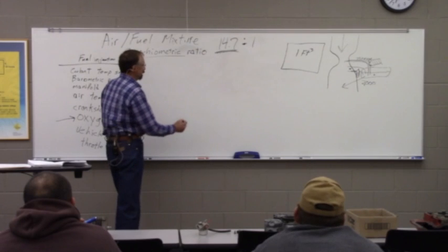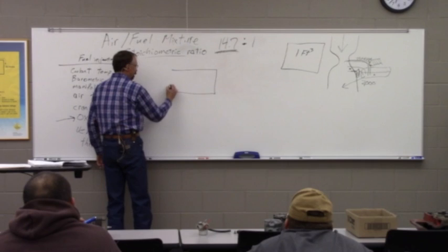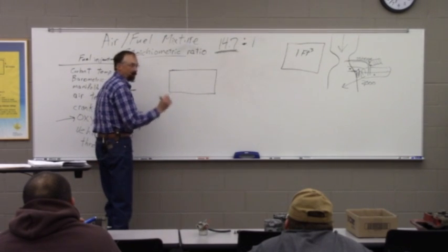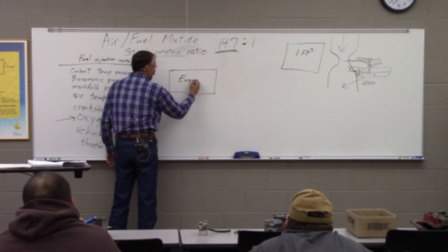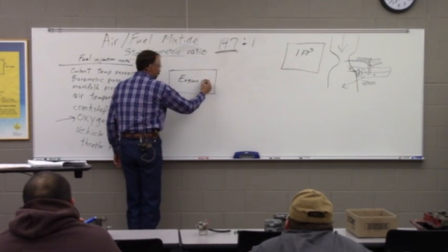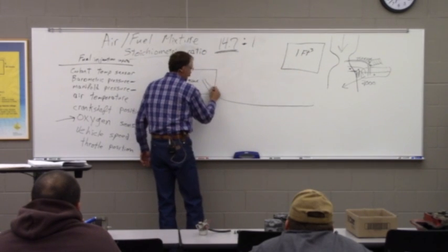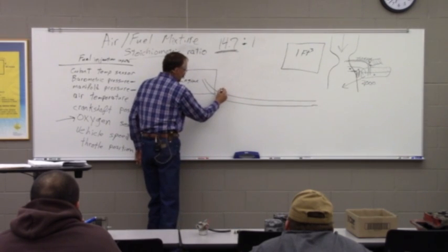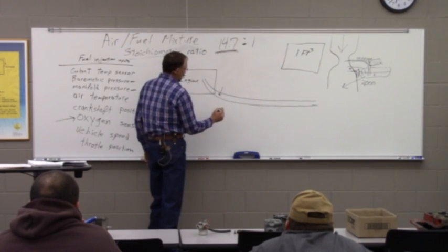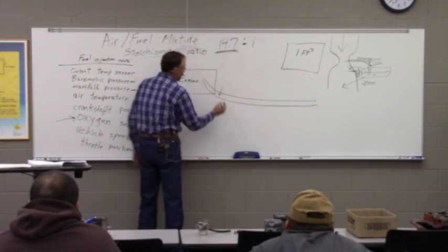So on the oxygen sensor, what we're doing, use your imagination with me a little bit. I'm not paid as an artist, on purpose. We're going to call this our engine, and our waste coming out of it, our exhaust, that's headed for the back of our vehicle. We're going to put this oxygen sensor right in here. And what it does, it actually creates electricity.